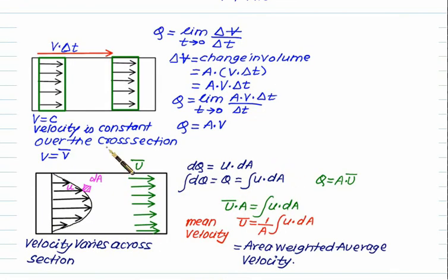But normally, due to the viscous nature of the fluid, the distribution is not the average velocity but rather a parabolic form of distribution. So whenever we have a parabolic distribution, the idea is to consider an elemental ring where the velocity remains constant and equal to u, with an elemental strip of area dA. For a circular pipe this ring is 2 pi r dr, and for a flat plate the area is width multiplied by dy.